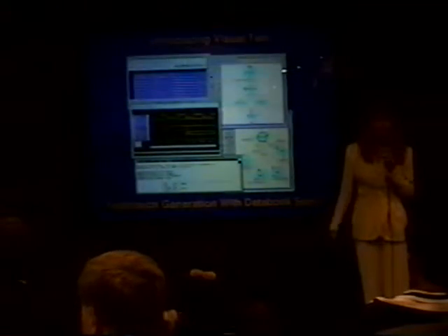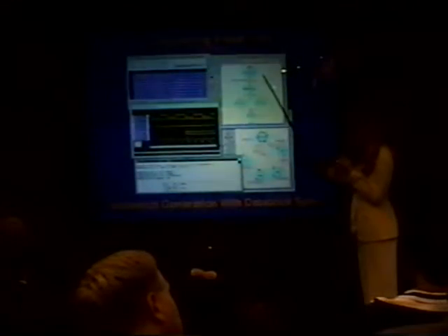And to help Verilog test bench generation, we're also introducing Visual Test, which lets you use data move timing specifications to generate timing-based test benches. Combining TDS's WaveMaker timing specification tools with Visual HDL's graphical HDL entry, Visual Test lets you generate complete test benches, pre-screened for production test compatibility.